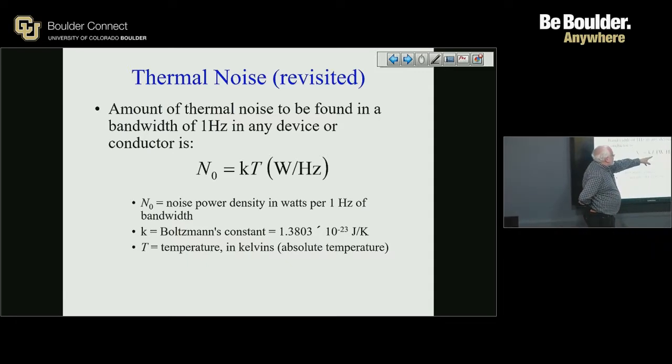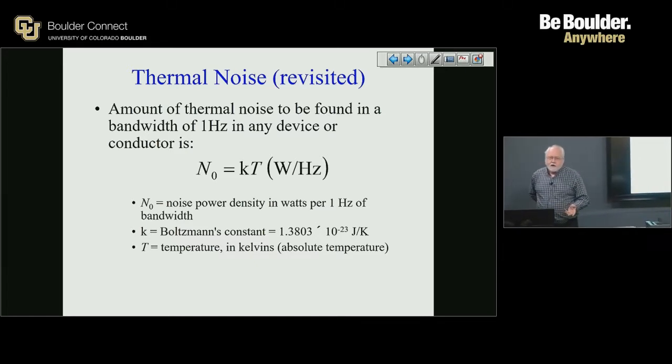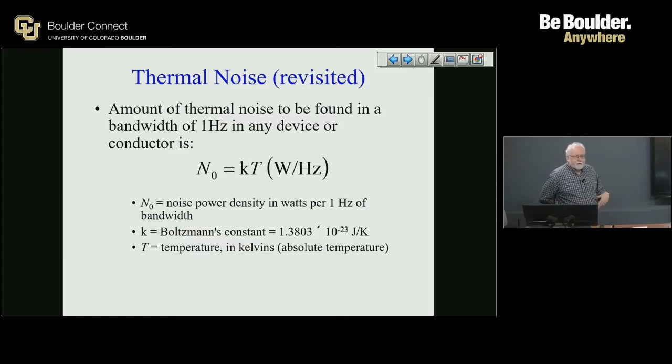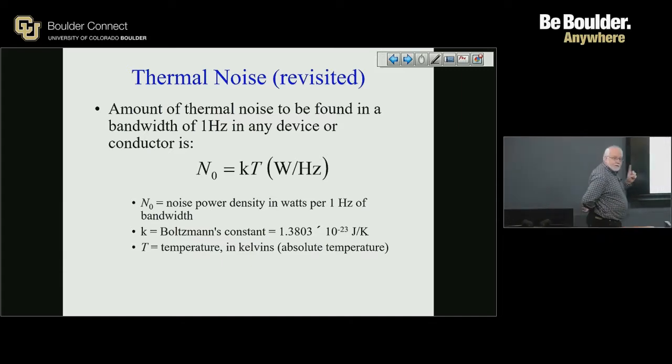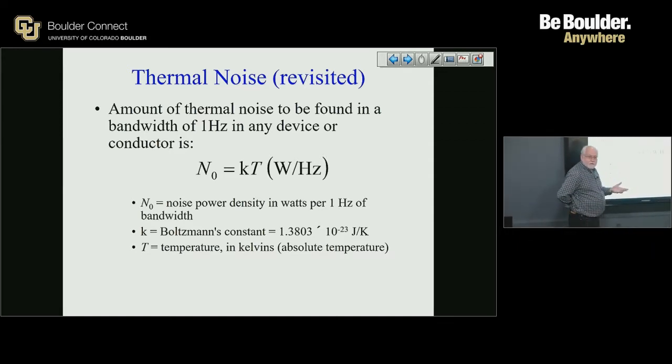For a Wi-Fi system, this is minus 174 dBm per hertz. So in a 10 megahertz channel, you're at minus 104, and in a 20 megahertz channel, you're at minus 103 dBm. That's the best you can do, but note that that's at room temperature, 27 degrees Celsius.